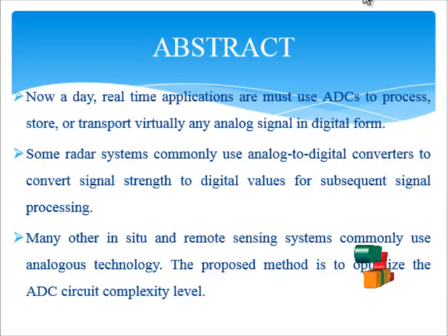Secondary sources are the gain error and the ADC transfer function, such as capacitor mismatches between the feedback capacitors, and the jump of the ADC transfer function. Either way, we get insufficient output due to limited settling, which introduces distortion in the SFDR.